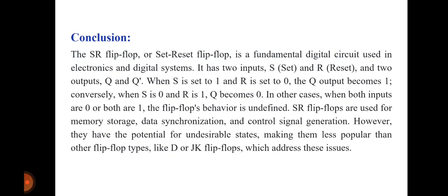Conclusion. The SR flip-flop, or set-reset flip-flop, is a fundamental digital circuit used in electronics and digital systems. It has two inputs, set and reset, and two outputs, Q and Q bar, which are complements. When S is 1 and R is 0, the output Q becomes 1. Conversely, when S is 0 and R is 1, output Q becomes 0.